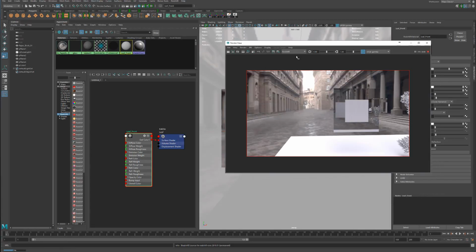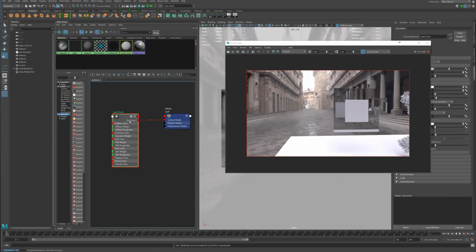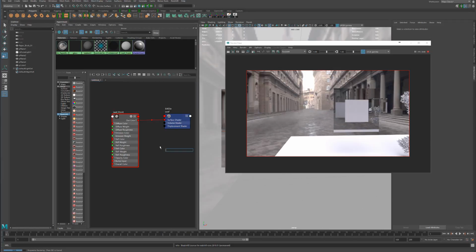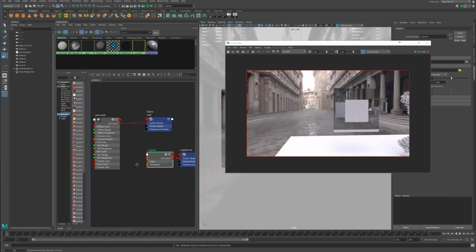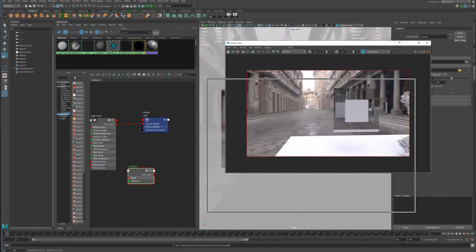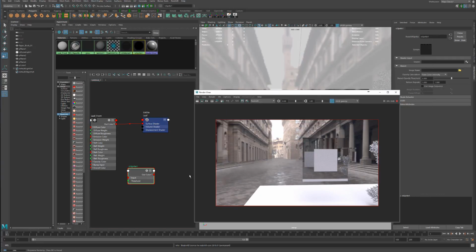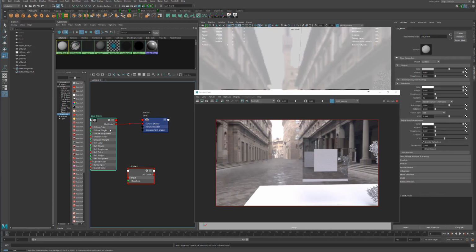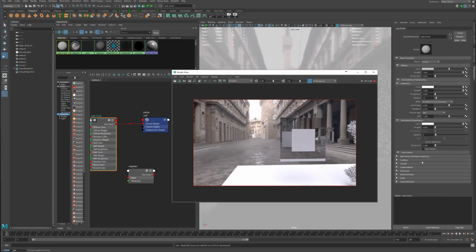To get things started, I'm actually going to start with the Sprite Shader to get our shape cut out. The Redshift Sprite Shader is used to make leaf cutouts or other cutouts where you just don't want Redshift to calculate anything outside of it.